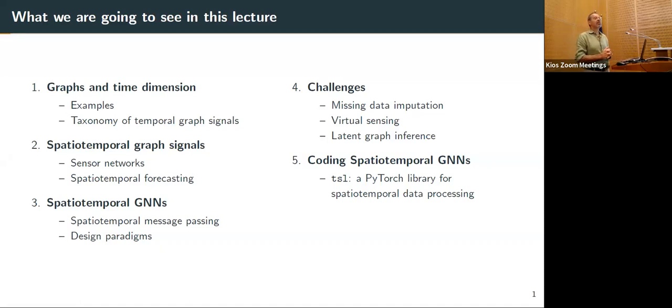Then we will see that in the real world, there are many challenges. One of those is that you are processing your data and you have a significant amount of missing data. So you acquire data and for any type of reason, not necessarily a fault at the sensor level, you don't get the data. It can be a problem with communication, the logger, or your server that was not updating the database. So you have holes. And what we want to do is to take advantage of the fact that we have dependencies to fill up those data: imputation.